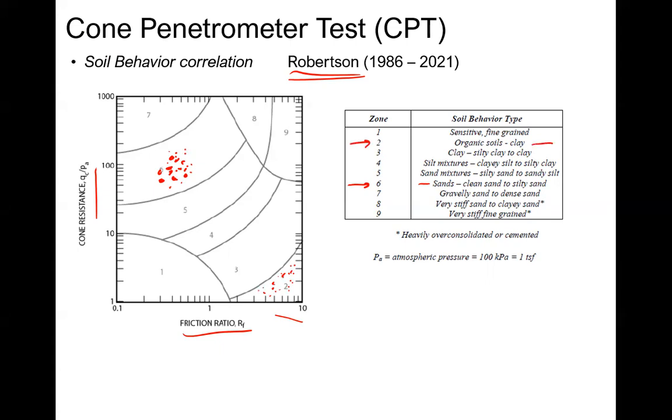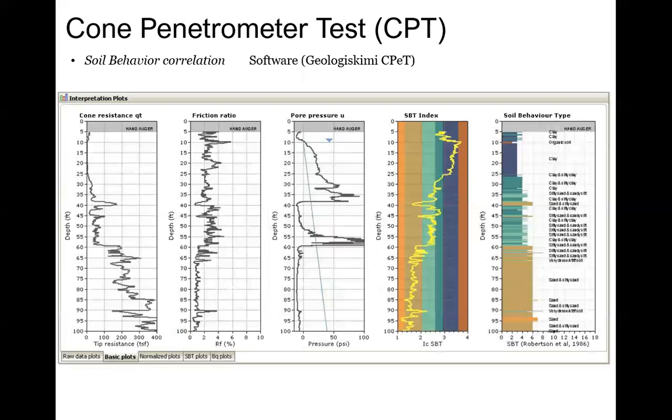And we would see, okay, this is most likely an organic soil or a clay. So this is only behavior though. We can't actually define the sample. But since this is all electronic, the benefit is now we can plot this real time. So there's software that will perform the CPT and take that data as it's being collected. And then I actually shoot out these really pretty soil profiles with depth. And this is again, while you're actually doing the test.